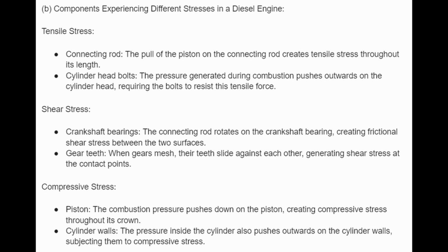Tensile stress. The connecting rod. The pull of the piston on the connecting rod creates tensile stress throughout its length. Cylinder head bolts. The pressure generated during combustion pushes outwards on the cylinder head, requiring the bolts to resist this tensile force.